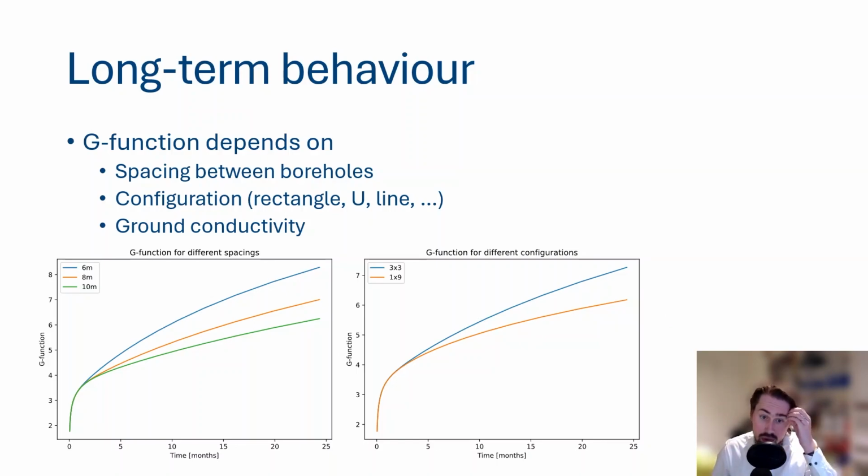So now you can say, okay, this is interesting, and we have just one time step, or should I say one unit step. But of course, we're not always injecting heat into the ground and not always at the same pace. So how do we go from this unit step towards a real temperature profile? And that we can do by something which is called thermal superposition.